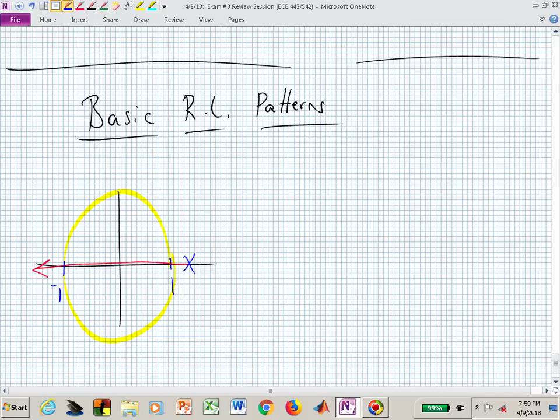Do you see that if you crank up the gain to get to that triangle, you would at least start to be stable? And if you kept K less than the K to get you to the box, you would remain stable. So here K is going to live between K box and K triangle. It has to be at least K triangle, and it can't get bigger than K box.